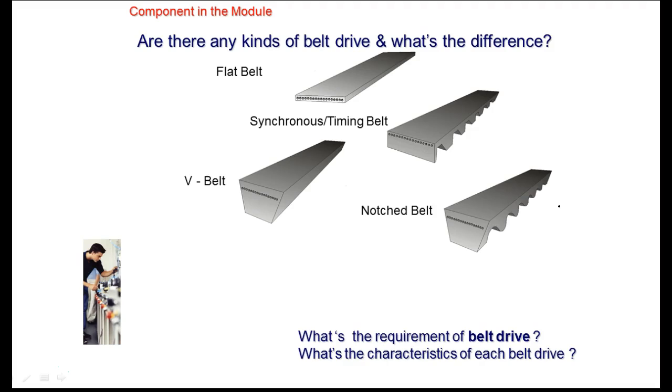What advantage does a notched belt have over a V belt? Well, it's got two advantages. It's more flexible, so we can have smaller pulleys on it than on the V belt. Another thing is it runs cooler. Why does it run cooler? It's got all those notches in there circulating wind, right? Then we have a multiple ply belt, which is basically multiple V belts that have the same back. Are we okay?